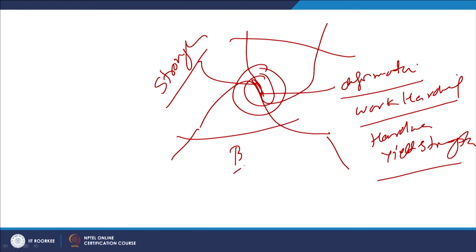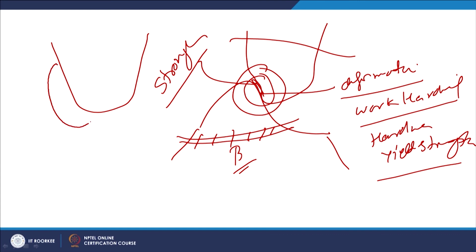If B is weak, then failure will occur from this side, and once this failure occurs, a small piece of metal from the component B side will be transferred to the component A side. So, this is the piece which will remain attached on the component A side.